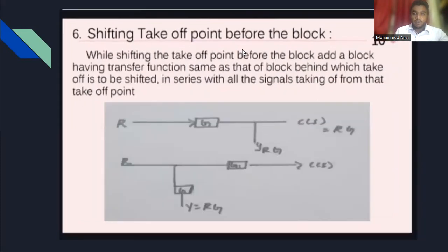Shifting takeoff point before the block. While shifting the takeoff point before the block, add a block having the same transfer function as the block behind which the takeoff is to be shifted, in series with all the signals taking off from that takeoff point.